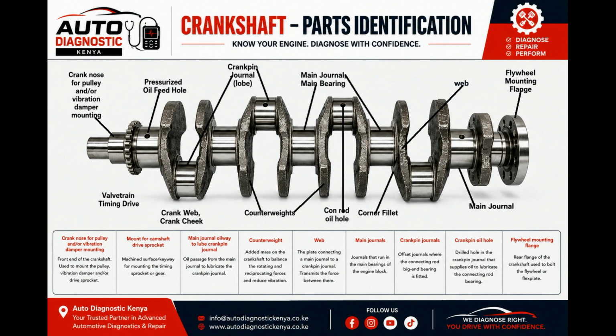Depending on the engine, it could be a timing gear, a timing sprocket for a chain, or a timing pulley for a belt. The crankshaft drives the timing chain or belt, which drives the camshaft. And this is where timing becomes extremely important. The crankshaft controls the piston position. The camshaft controls the valve position. Those two have to remain synchronized. If they don't, the engine cannot operate correctly.